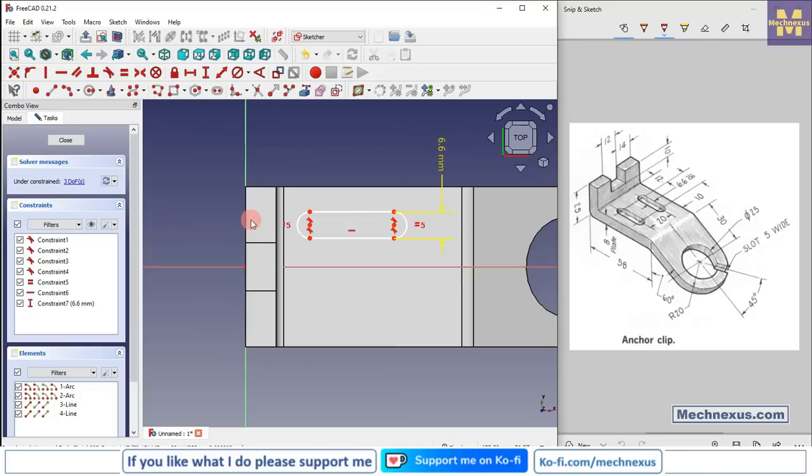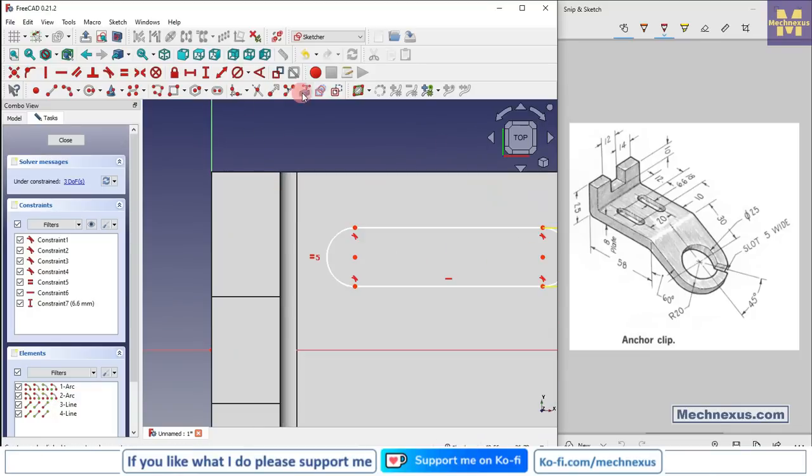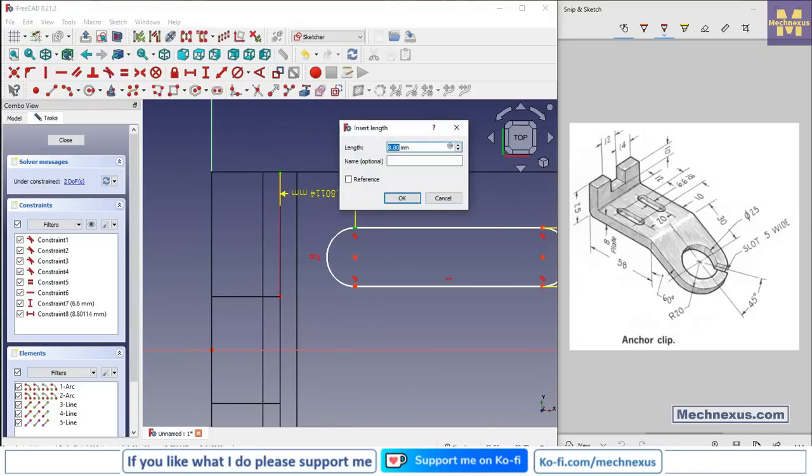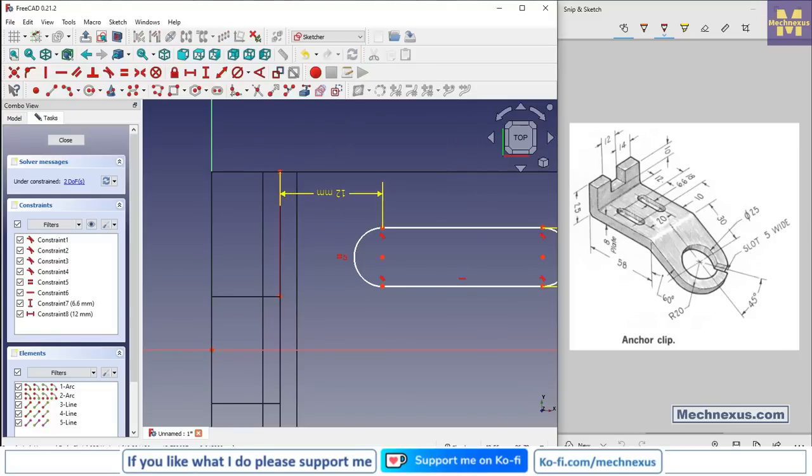And now we will select project edge and select this, and here we will switch to the wireframe, select horizontal dimension, select this and this, and add the value of 12 mm.